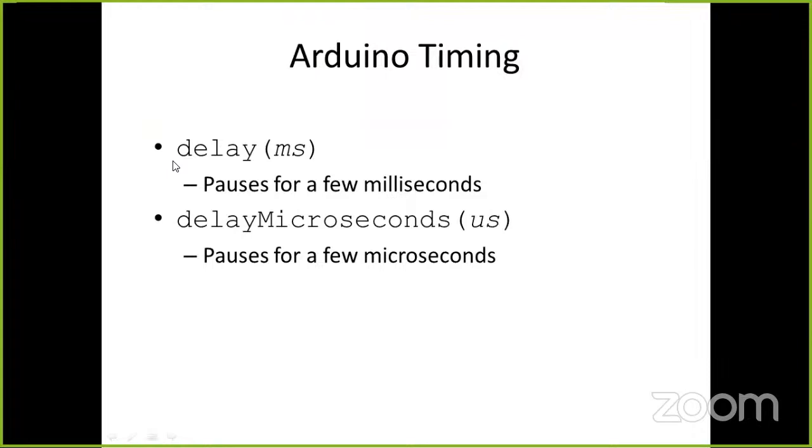So now the delay. Whenever we use delay in Arduino code in C++, we have to write it in milliseconds. And whenever we use delay in Tinkercad, we can directly use it in seconds. So that is about the delay, that we can use it in microseconds or simply milliseconds. So when we are writing code and writing delay or some value, the value we are writing over here is in milliseconds.